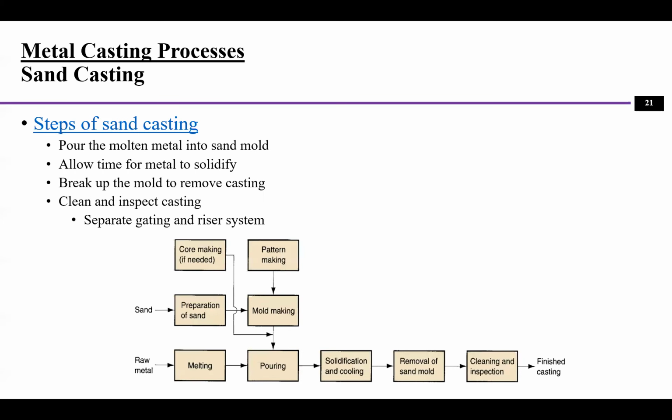Another type of solidification process is to deal with the metal materials. And typically, in metal shaping, we call them a casting process. How the casting process works is, first we have a pattern. Pattern means the product you want to make, but it's not the product. It's made of some other materials to create the shape of the product that's used in the mold.